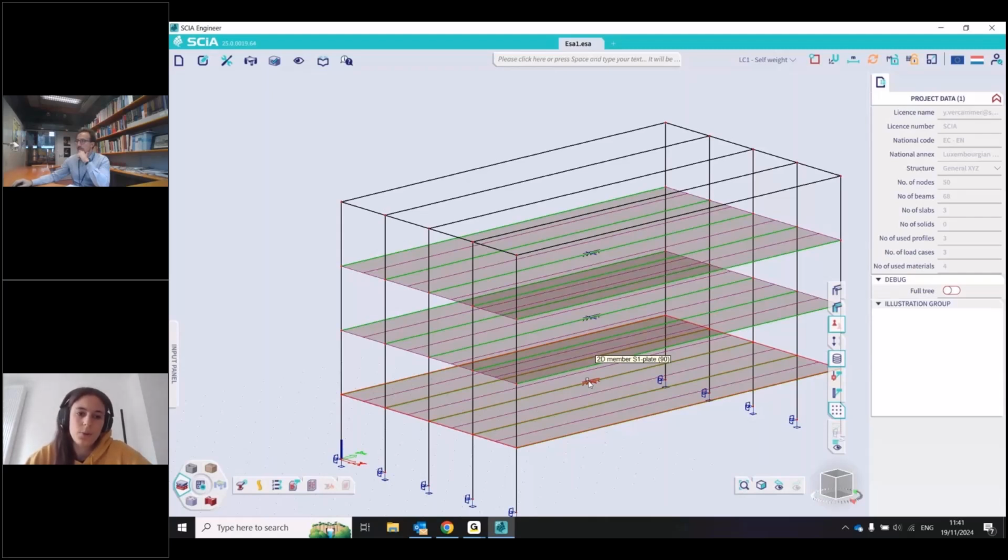So to consider that these beams are actually linked to the composite deck and they are working together as some composite beam unit, we need to connect these members as ribs. This also allows you to have some beams under your composite deck that don't have shear studs and are not connected, and to still calculate these and not automatically have them considered as composite beams, right?